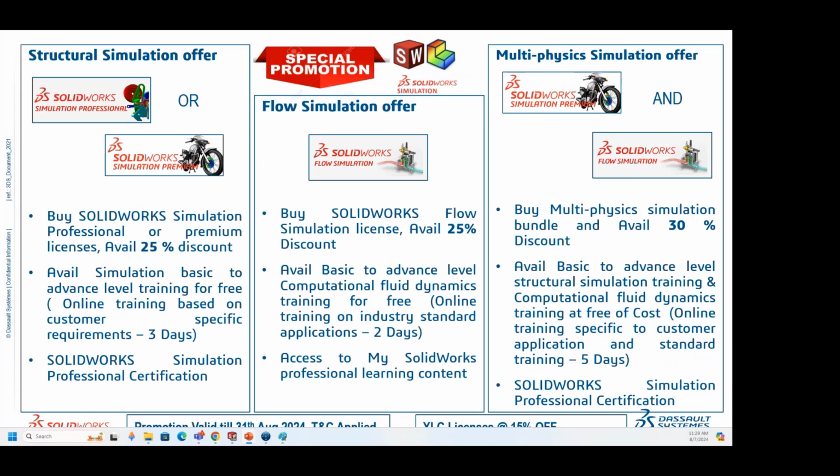This is basically the linear first stage you perform when you have a slender member. First you have to perform a static analysis for your loading. If the slender member is subjected to compression and you believe there is a chance of buckling, the structure is going to buckle. Then you have to set up a buckling simulation and take out the buckling factor of safety. Then you have to correlate your results with respect to the yield factor of safety and the buckling factor of safety. Then you have to come to a conclusion, right?